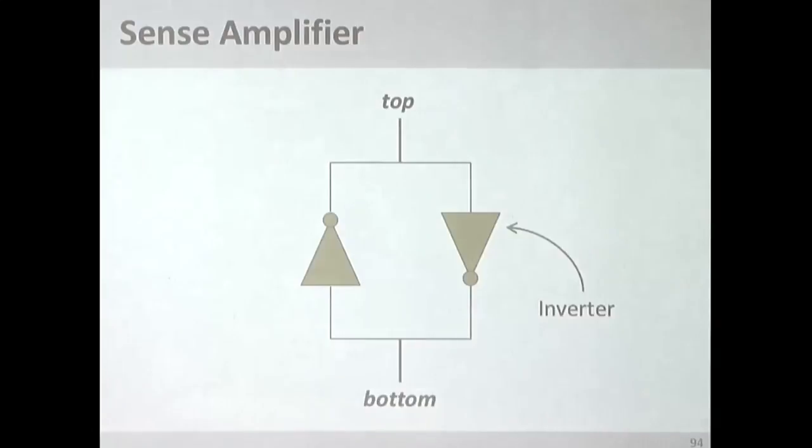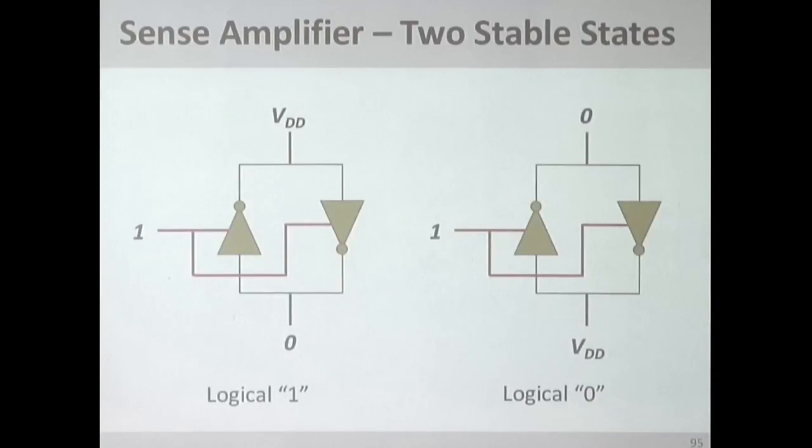So let's start with the sense amplifier. I'll start again at the bottom. So basically, sense amplifier has two inverters, cross-coupled. This is hopefully clear. It's actually an SRAM cell, the way you look at it. And it has an enable logic over here. When you enable it, it basically has two possible states. Either this part is VDD or this part is VDD.